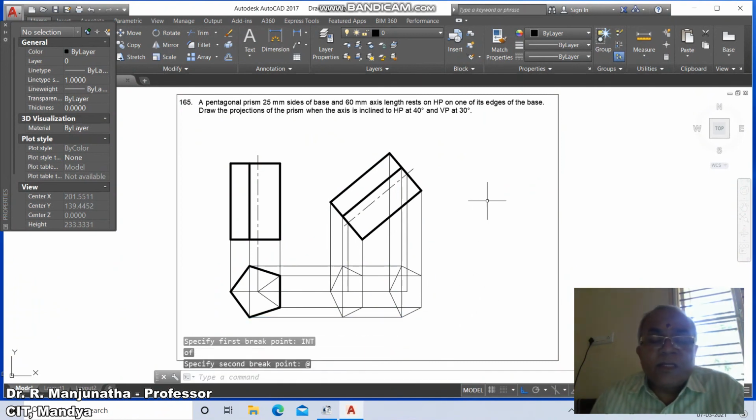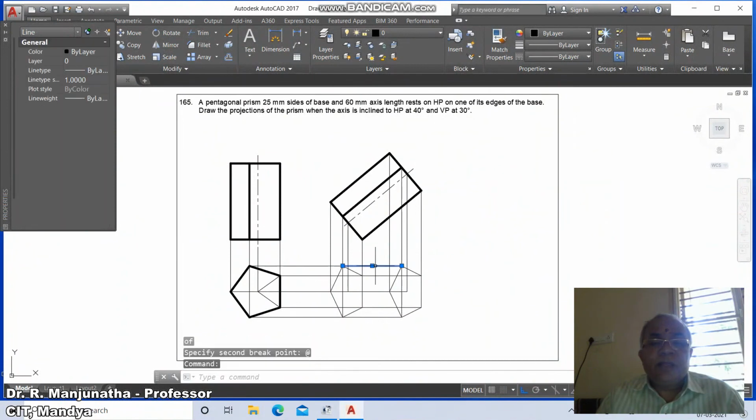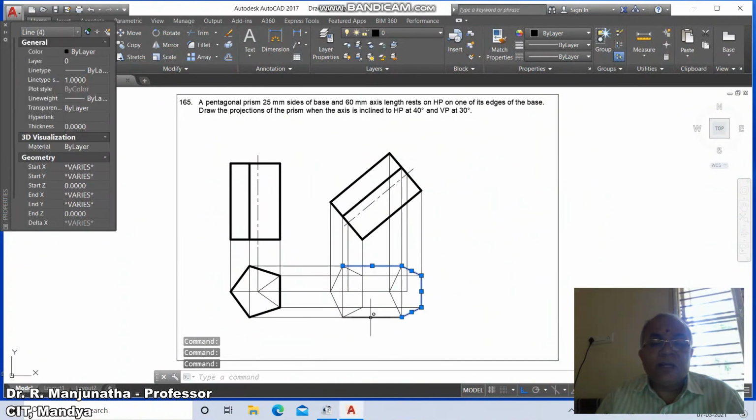So now all the exterior edges of the boundaries of the solids are visible. You select this line, this line, this line, this line, this line, and this line. And the surface, when you're looking from top view, this top surface is not the observer, so that surface becomes visible. And this line, and also this line, all these things you change to the visible layer.